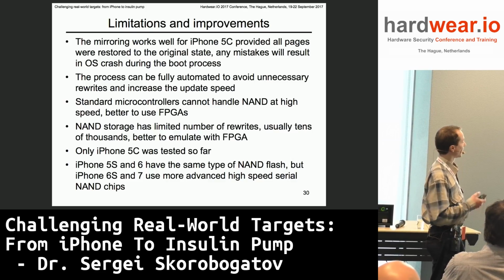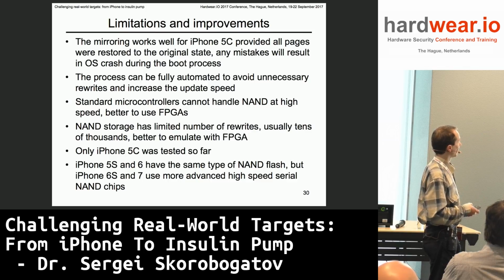Also, the communication speed of the microcontroller was relatively slow, so you have to use some hardware solutions based on FPGAs to make it faster. Another problem is that the NAND storage cannot handle many thousands of rewrites, so you ideally would like to use some kind of emulator on FPGAs to emulate the NAND protocol and then restore its contents.